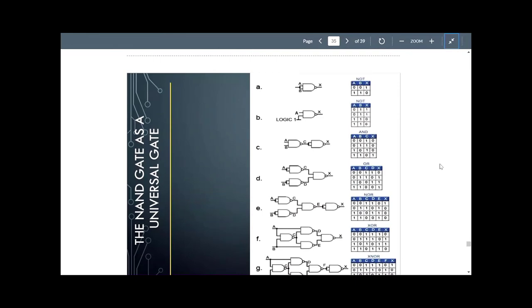If you look at the bottom block diagram, each individual gate in the top block diagram represents a sub block. We got exclusive OR right here, and then you got an AND gate right there, and another AND gate below, and you got an OR gate. All those individual gates were built using NAND gates.